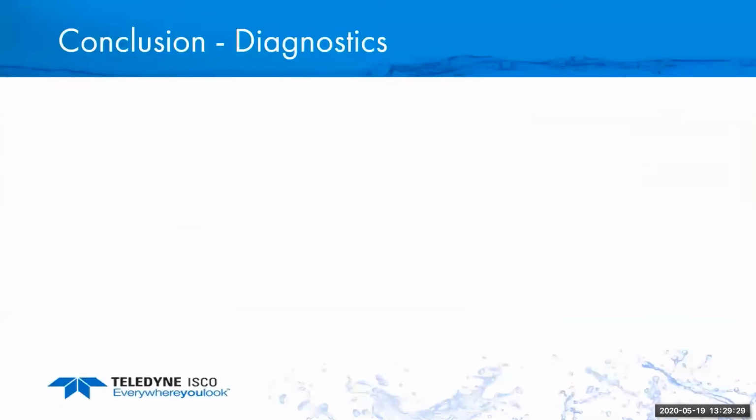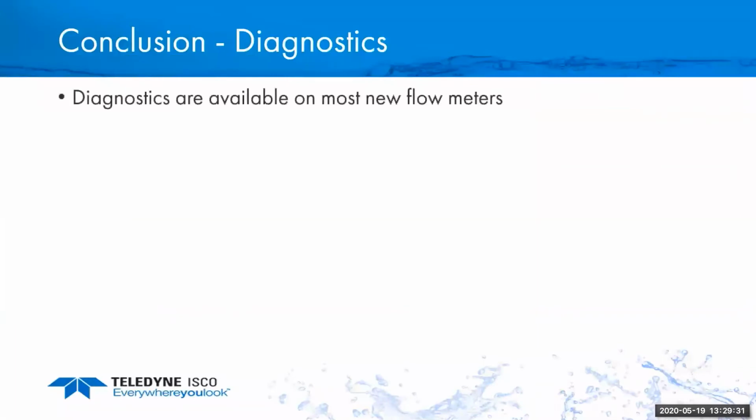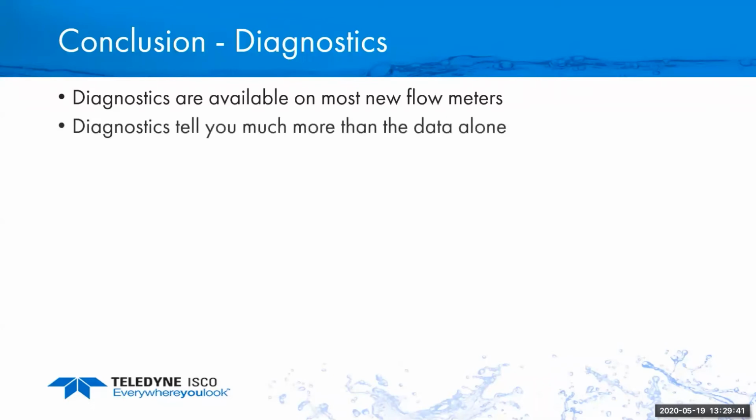Okay, so I'm going to go ahead and wrap it up here. Diagnostics should be, if they're not, available on most new flow meters that you'll find in the market. And I would highly recommend buying something that has that capability, because the diagnostics are going to tell you way, way more information than just the data alone.